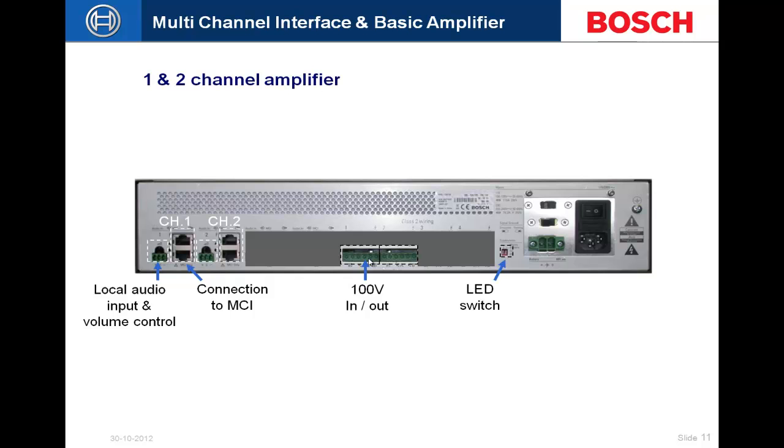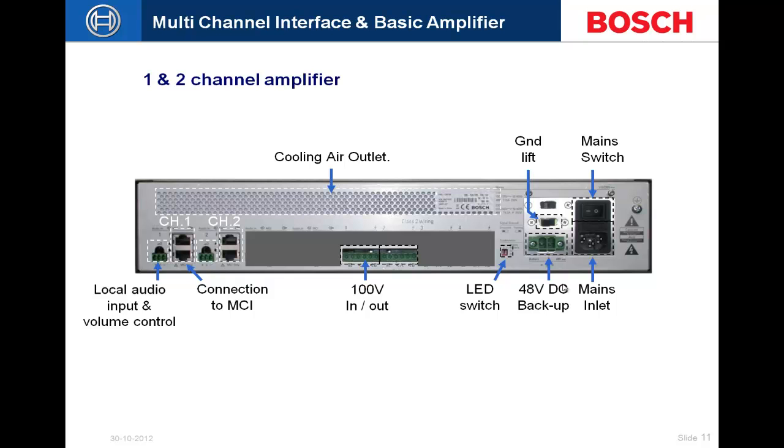Our 70 volt, 100 volt output here, our LED switch giving me the ability to either supervise mains or battery power sources. Mains inlet, mains switch, ground lift switch is available. It's also switchable between 110 and 230 volts, and it does have our 48 volt standard DC supervised input as well.